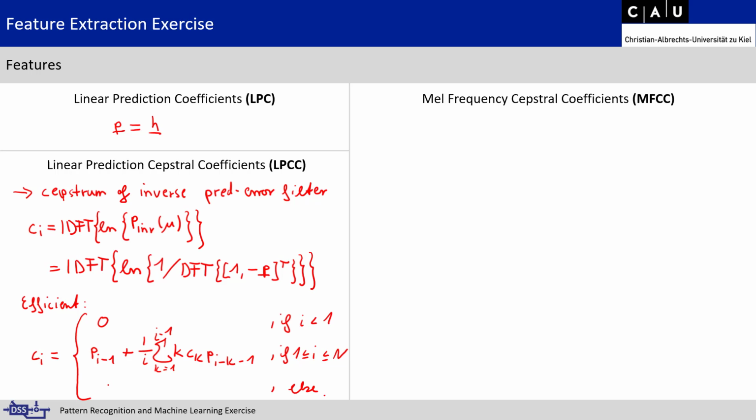And then our third case is actually exactly that sum, but because we've run out of prediction coefficients, we don't add the sum to a prediction coefficient, but it's just this very sum. So it's just the second part of the line above. Okay, this is then everything you need to know about LPCC features.